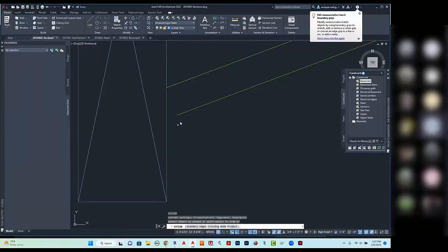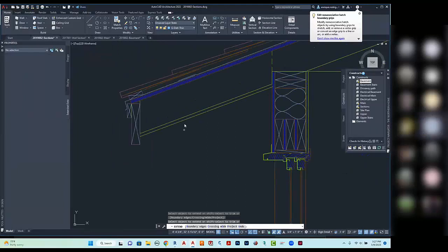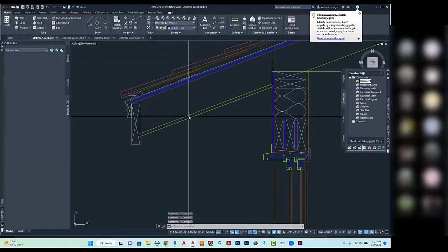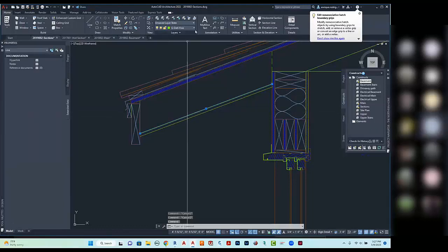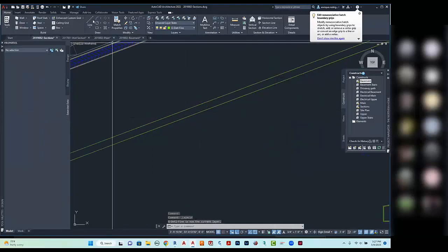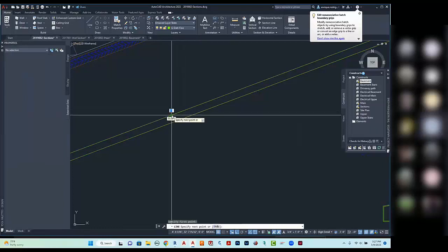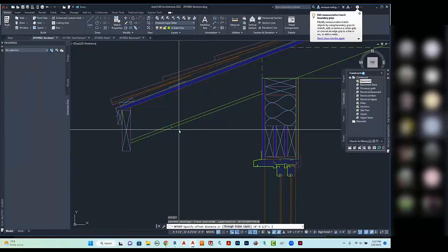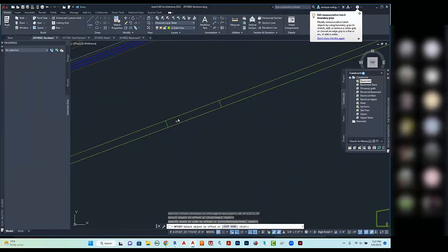Go ahead and extend that right into here. And I'm going to show where that vent might be in here by, number one, changing to this layer, and laying out a line somewhere here, perpendicular. Let's go ahead and offset 4 inches. May not need to be that much.